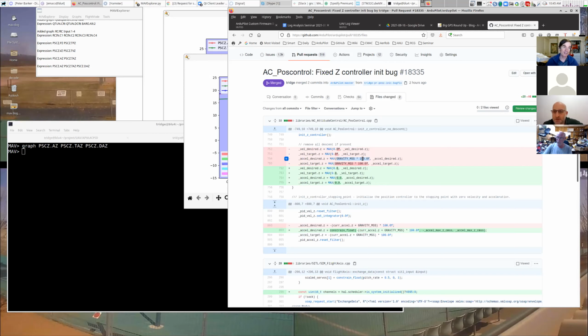And now, of course, we've got a second bug, which is we notice that our true airspeed innovations are always 0. For this particular type of unusual aircraft, we're not setting the forward flight mode flag correctly to the EKF, which means we're not taking advantage of our airspeed properly, and we are not taking advantage of things like sideslip fusion and wind estimation and all the other good things you get by having wings. So we will enable that as well. I'll need to do a patch for that.